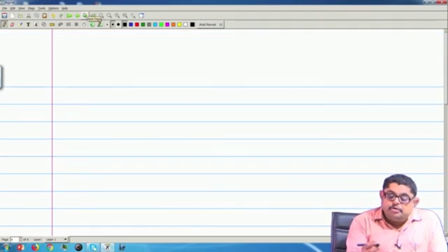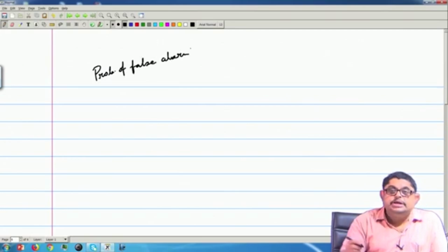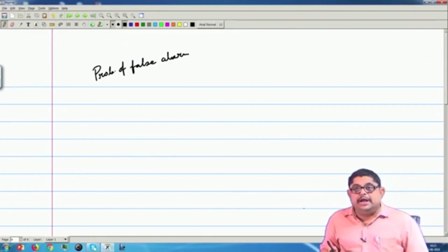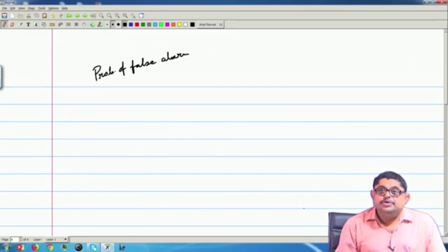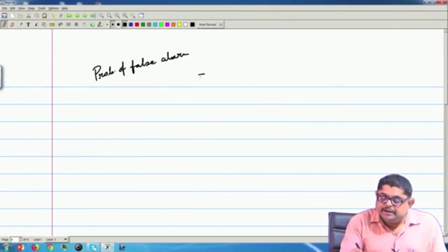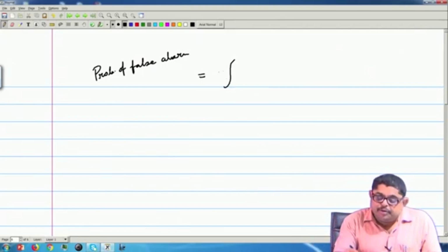Okay. So, this is about the decision distribution properties, but let us come back to our probability concept. Now, let me define what is probability of false alarm. What is a false alarm? No signal is present, but noise is substantial and the radar is saying that there is a signal. In our mathematical terms, the signal is absent, that means it is a Rayleigh distribution case.